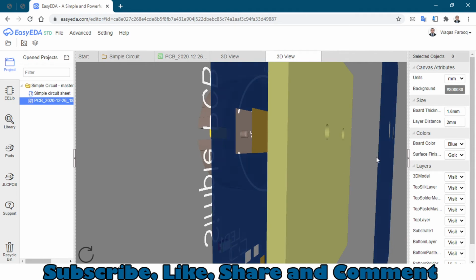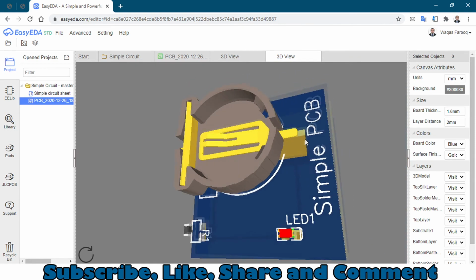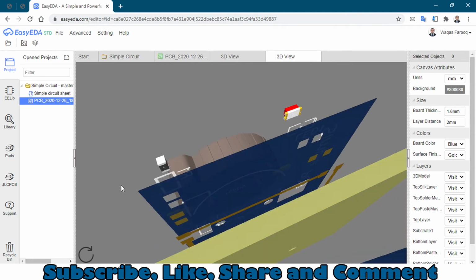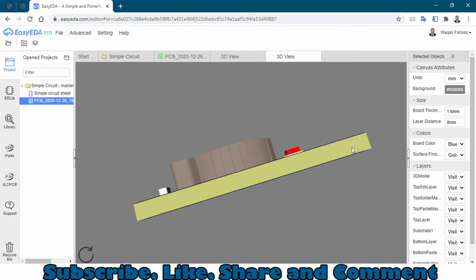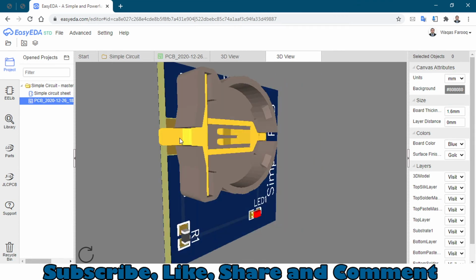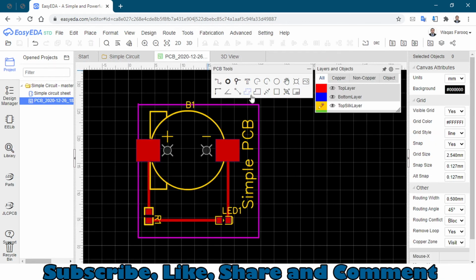As you can see, this is a bottom layer, this is a PCB, and these are the copper tracks, and the top silk layer, text, and all the components are raised at a certain level. So you can bring them back by just changing it to 0, and they will merge together. This is how you can make a simple PCB circuit and check how it will look in a 3D view. This is the old 3D view and this is the new one.